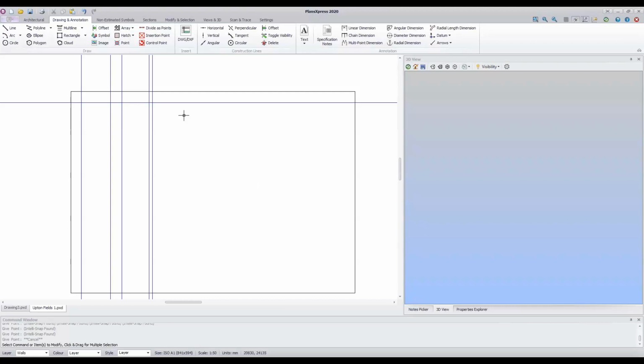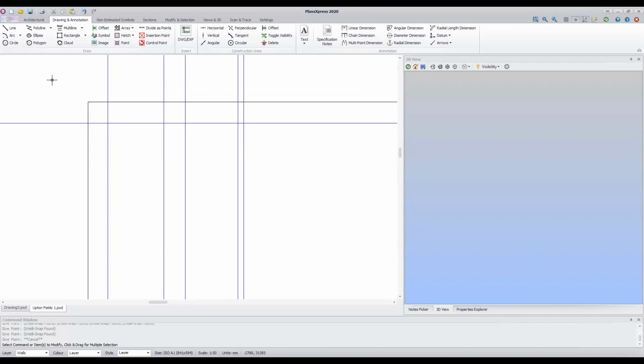external walls. So I'm going to zoom in slightly on the top left-hand corner of my screen. So I'm going to place my cursor over to the top left and scroll towards the screen. That will help me zoom in. So I've now got a couple of other horizontal construction lines to add. So to do that, we click the horizontal construction line button as before. So we're going to place a horizontal construction line 1000 mil before the top horizontal construction line.